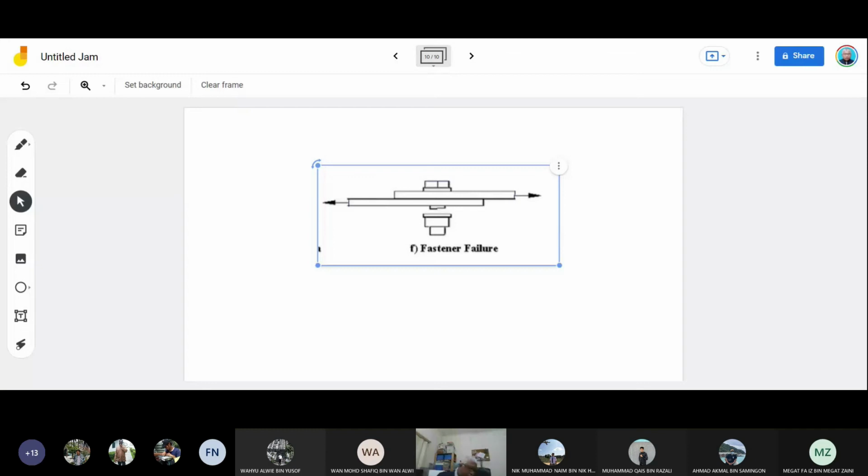Most large transport aircraft structure uses lock bolts, which are stainless steel pins. But for rivets, we still use aluminium, for example 2117 aluminium. However, for this analysis, just to keep things simple, we may still consider the same aluminium, 2024.